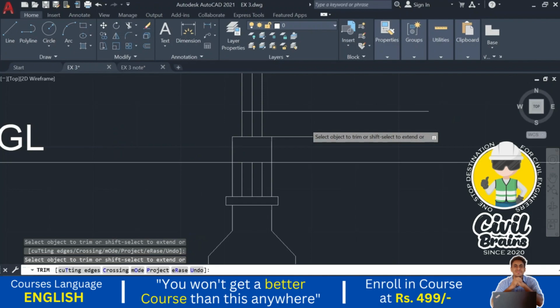Okay, a 0.1 meter thick PCC we have provided. So above the PCC, we need to provide the footing. So what is the size of the footing? Sorry, this is the width of the foundation. Exactly correct. So the width of the footing is 1 meter and the width of the foundation is 1.2 meters.